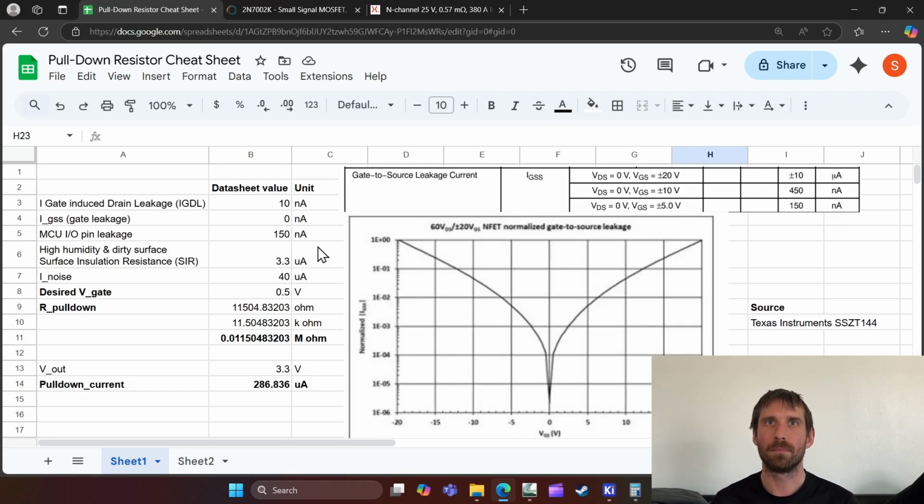So also keep in mind, we're dealing with worst case here. My microcontroller pin is going to be configured as an output, but not all the time. What if that reset pin is triggered? What if I'm programming the microcontroller? What if at initial power up, it's going to take microseconds, nanoseconds, whatever time it is to configure that pin as an output. So in those scenarios, this is an input or high Z, high impedance. So this must be accounted for.